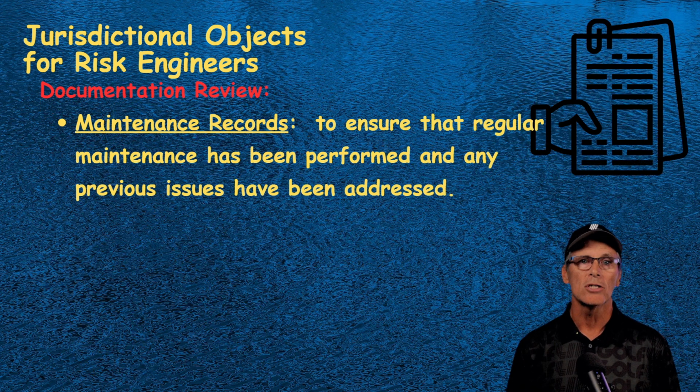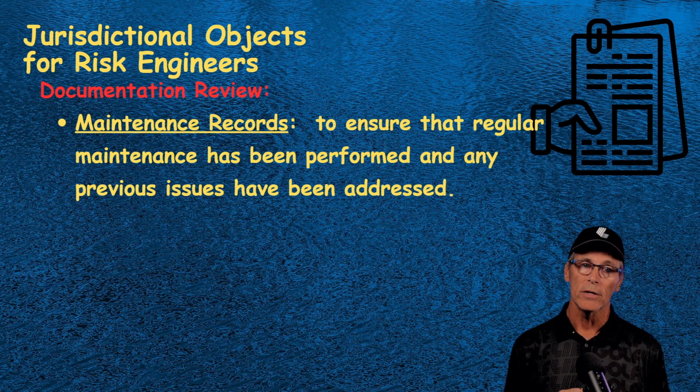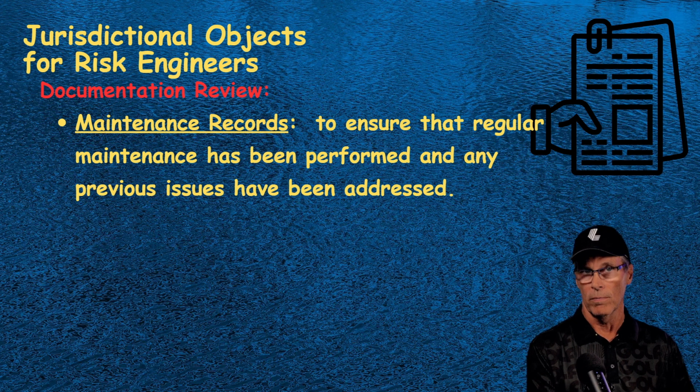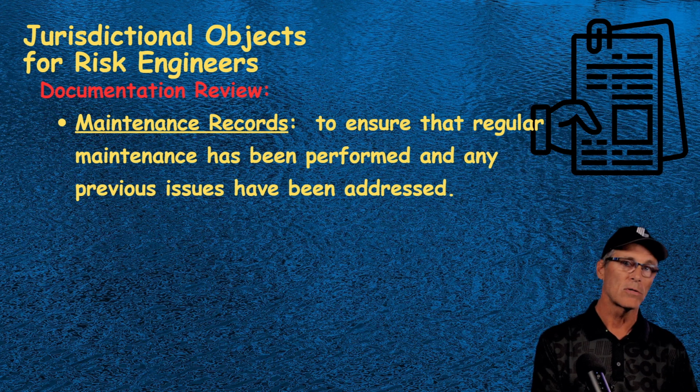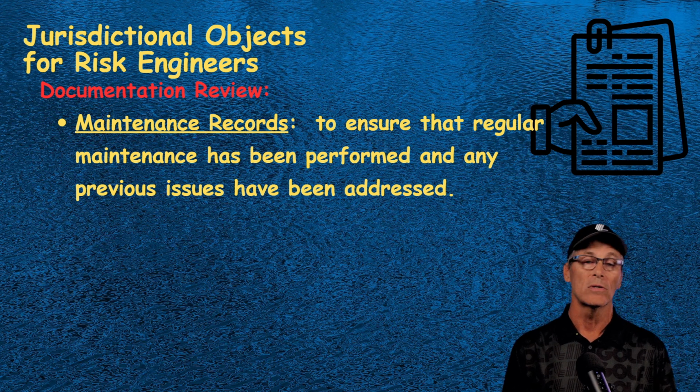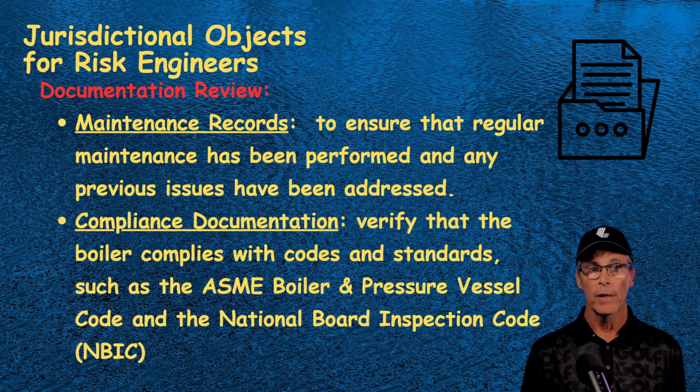Next, we're going to do documentation review. We're going to look at the maintenance records. We're going to see was this equipment maintained properly? When it failed, was it repaired properly? Was it inspected properly after the repair?